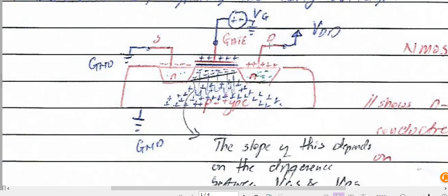When you put a resistor in series in this link, it is going to have a voltage, and the voltage in the resistor is going to be equal to VR, and VR is going to be equal to ID multiplied by R, which is VDD minus VDS. Since the voltage across the resistor is the potential difference between the supply voltage and the voltage in the transistor, you're going to have a specific amount of current flowing through this.